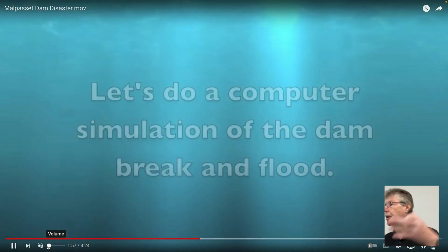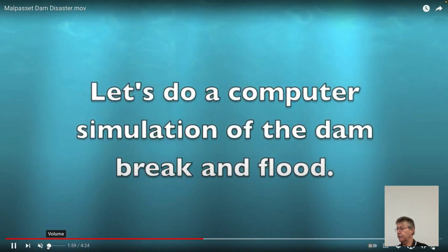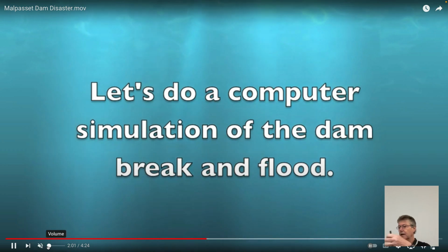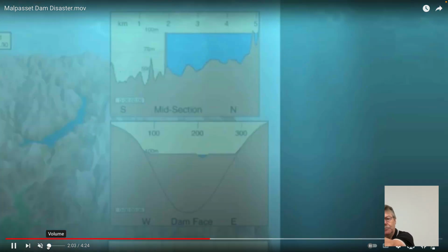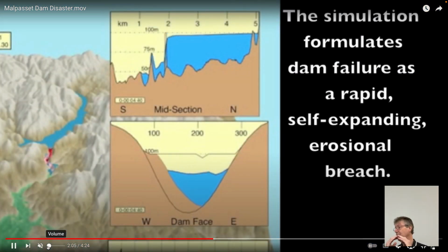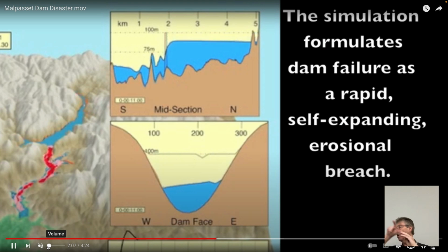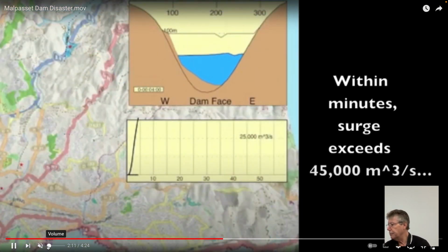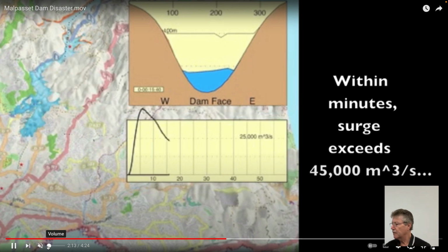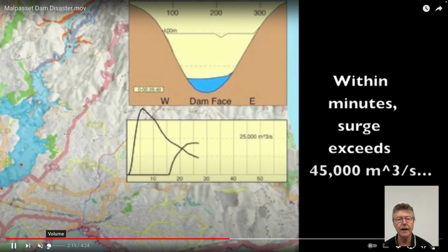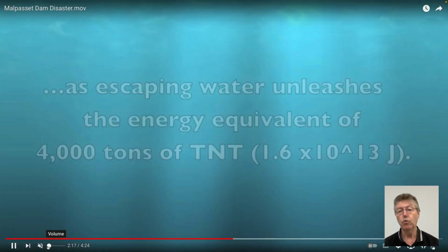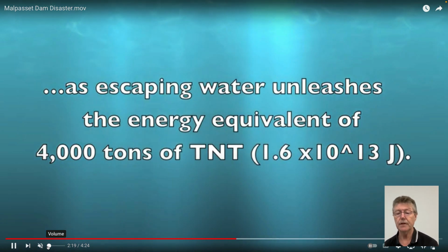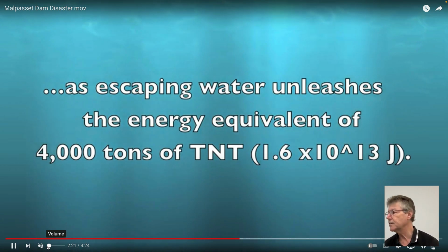It moved because of the abutments that support the arch dam, right? So the arch dam is arched upstream, so you're pushing against the arch, just like a stadium roof is arched that way. Structurally, it's quite sound. So it relies on the abutments that it pushes against. They actually moved, and the dam cracked, and as a result, the water went downstream, and so on, with not very good results at that time.